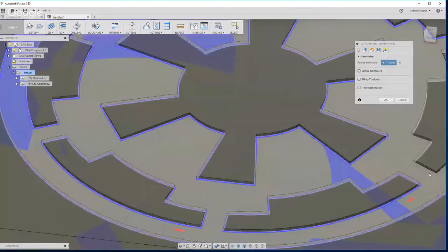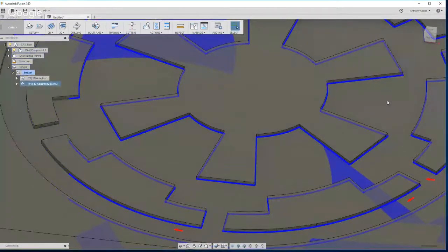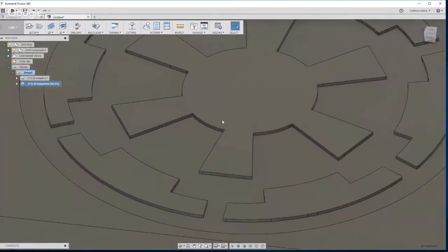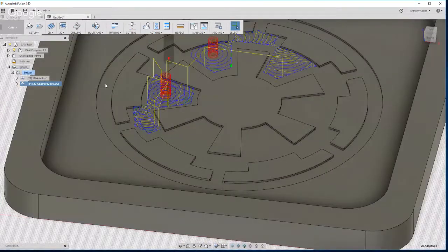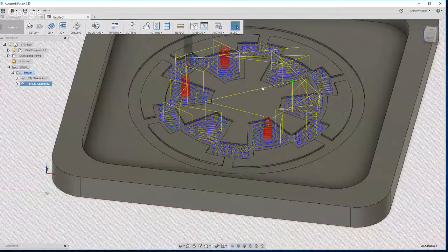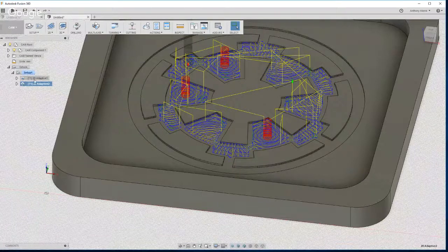So if I choose that on each of those, say OK. It'll use the exact same settings, which are fine. It's all I need. It'll clean out the bottom nicely and use the same tool, same settings. So it's just generating a nice toolpath. Now you can see it can't get in between all of these little areas here. That's all right. This is just clearing out the bulk of the material.